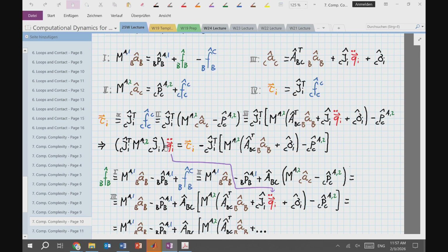We've seen this when we talked about collisions, right? Our space was here, we had our contact space mass matrix, right? Now this is the inertia that the joint sees, right? That's a physical quantity. If this is a pure rotational joint, this is a scalar quantity that has units of kilogram meter squared, right? It's an inertia. And you can immediately see there's a linear relationship with, what torque do I apply, what accelerations do I get. Projected into yet another space. Same thing now, 4th time.